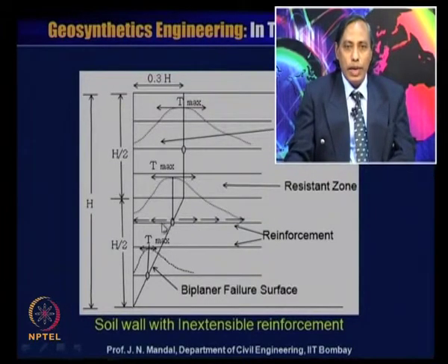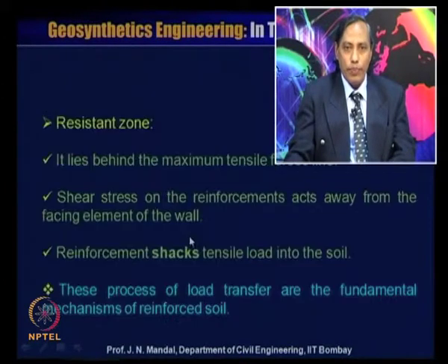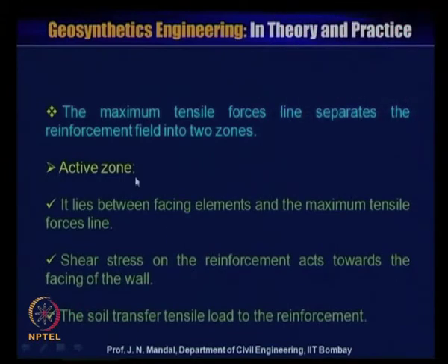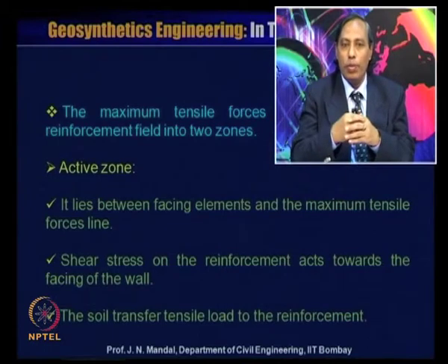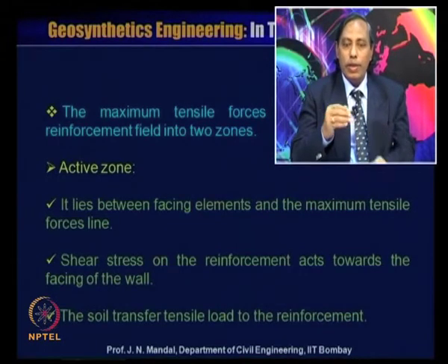So, you can see how the shear stress moves toward the facing element, whereas in the other zone shear stress moves away from the facing element. The active zone lies between the facing element and the maximum tensile force line, and the shear stress on the reinforcement acts toward the facing of the wall. This means the soil transfers the tensile load to the reinforcement.